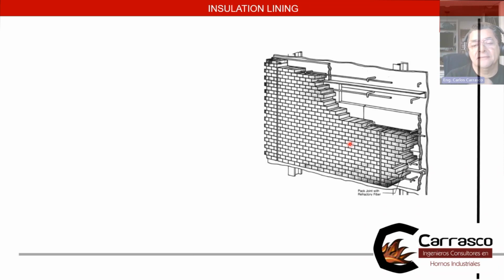So we have to decide if I am going to use a hard brick, or I can use insulation brick, which is softer and more expensive, but it's better to isolate the heat from the inside of the furnace. How I'm going to anchor the bricks to the walls, because they will expand. You can see here this line here. And here, this is expansion provision. So the materials will expand, but it will not fail during the heating time.